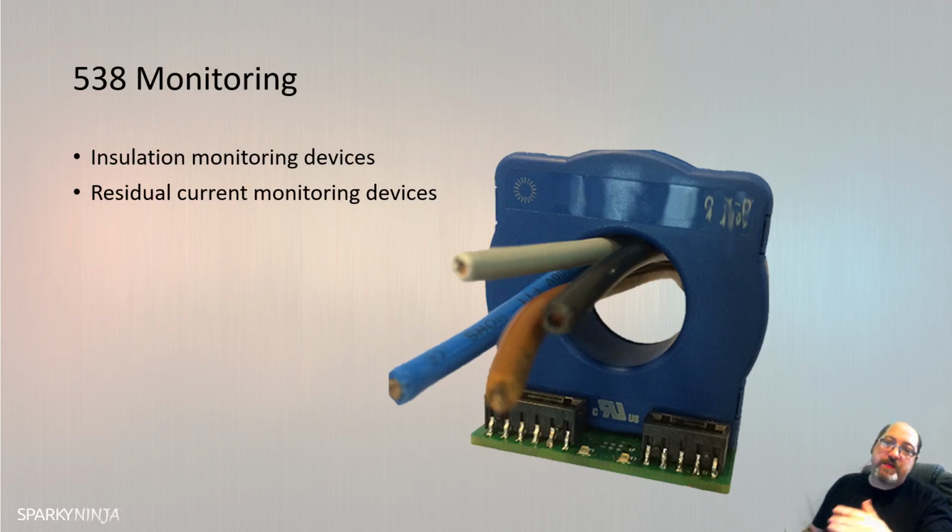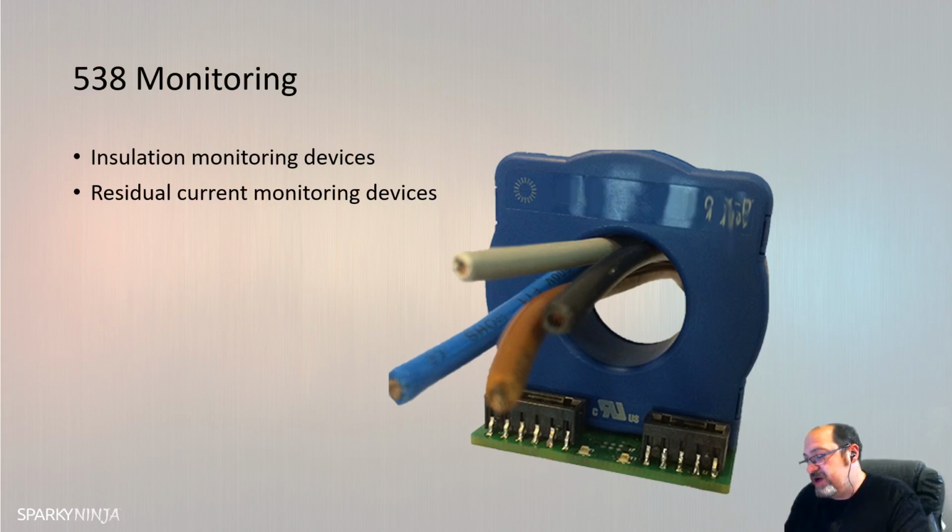And then the other type of monitoring device that we have in here is the RCM, the residual current monitor. That's quite quick and short there. An RCM permanently monitors leakage and fault currents to earth of the downstream installation or part thereof, and is intended to inform the user about the level of these currents of that part of the installation being monitored. They're not intended to provide protection against electric shock because they are a detecting device. They are not a disconnection device. They just detect.